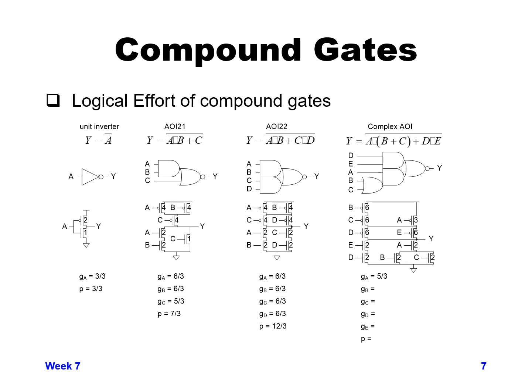For B, we have a size 2 NMOS and a size 6 PMOS, so that will be 8/3. For the input C, it's the same as B, so we should get 8/3. D is also the same, but it's a slightly different series device, but it's a size 6 with a size 2, so it's also 8/3. And E is size 6 and size 2 as well for 8/3.